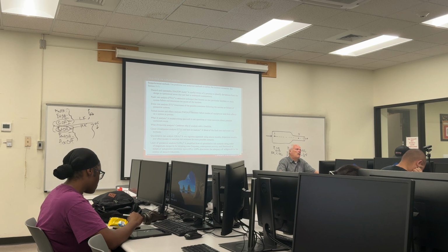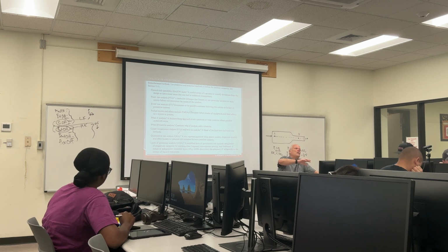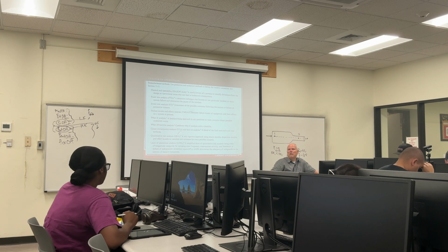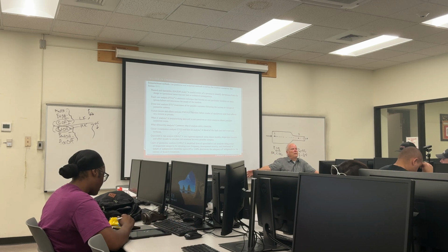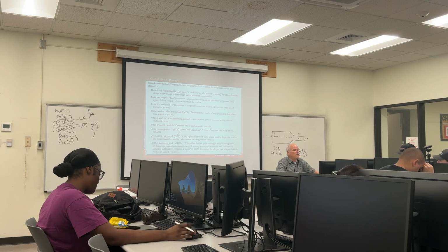Then there's fault tree analysis and event tree analysis, which are kind of looking at it from two different directions. One looks at the failure and sees what it could cause. The other looks at the event itself and goes back to what failures might have caused it.